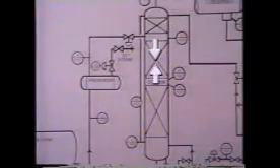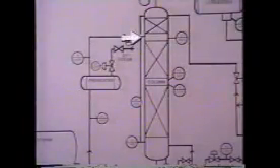The first of these problems is overloading. Overloading occurs when the flow of liquid down the column is so great that it starts to block vapor rising up the column. This can be due to a number of causes. For example, feeding too much mixture into a column can cause overloading. The excess mixture entering the column increases the hydrostatic pressure across the trays, blocking the rising vapors.